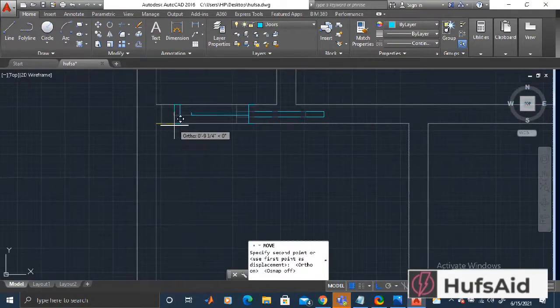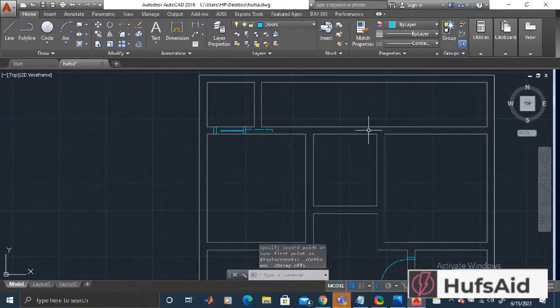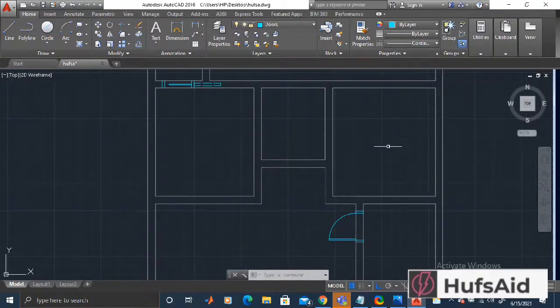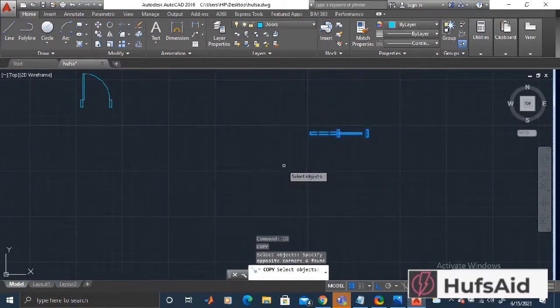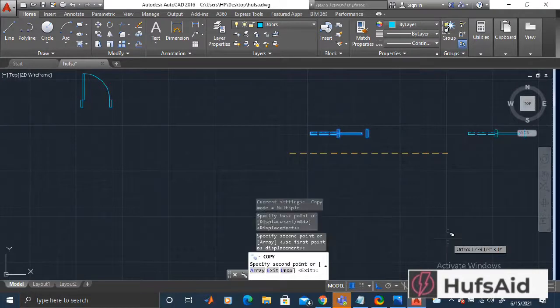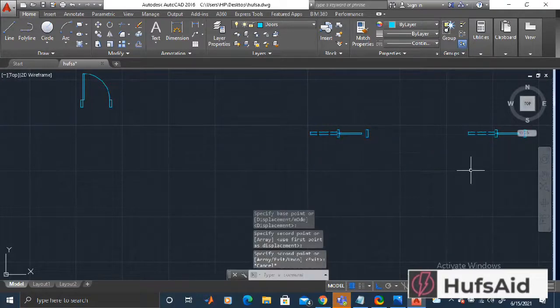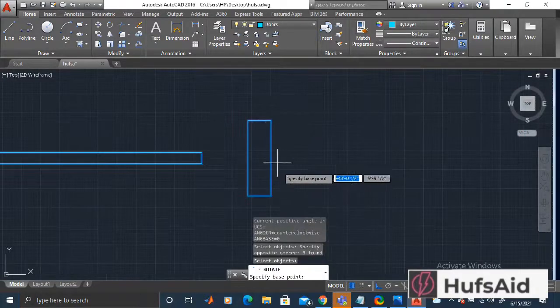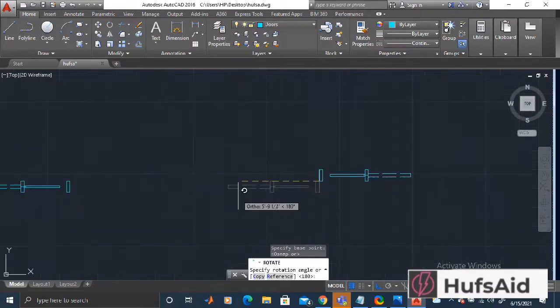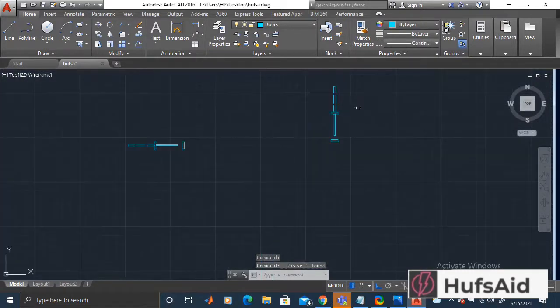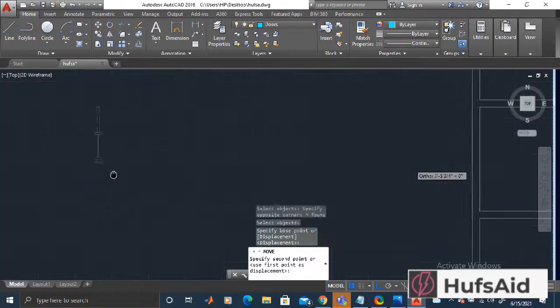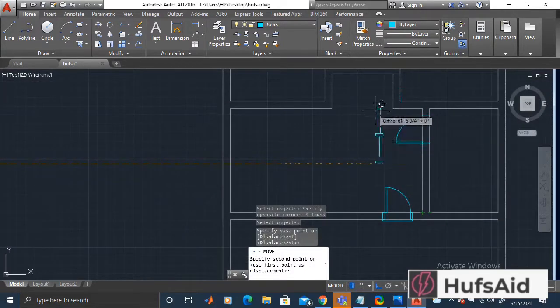It is interesting to note here that if we replace a swinging door with a pocket door, it recovers at least 10 square feet of floor space around the door. And also, it frees up real estate space on the walls for fixtures and other artwork. But as we have already discussed, we cannot have any conduiting going inside those walls. So there are pros and cons for the pocket doors. But for such small areas, pocket doors are usually preferred over the swinging doors.